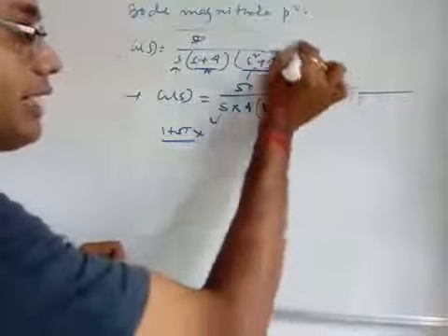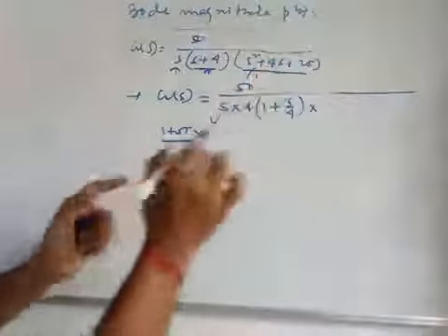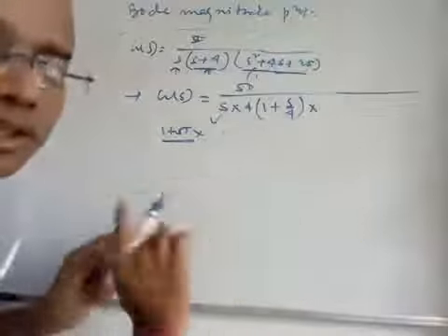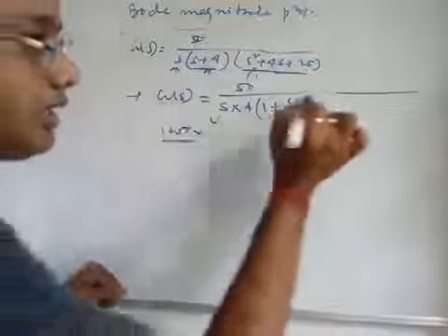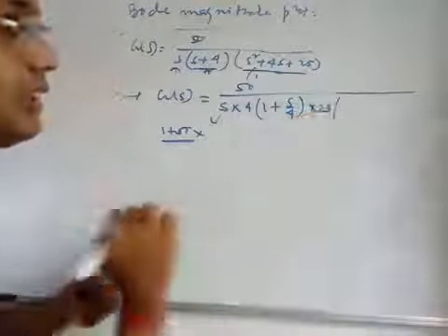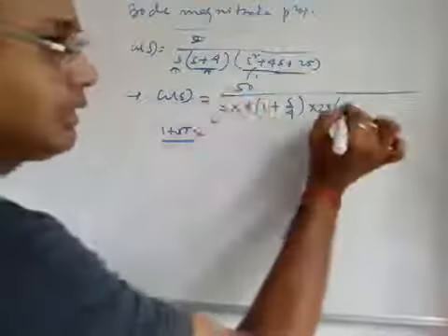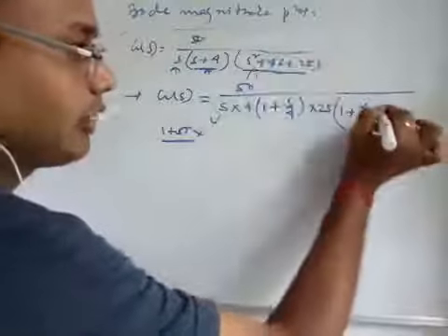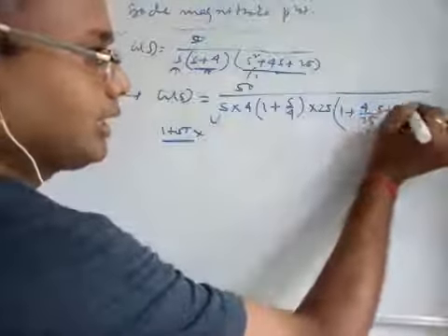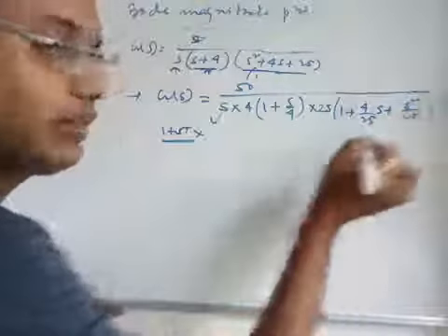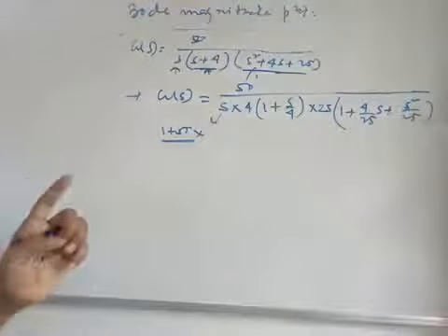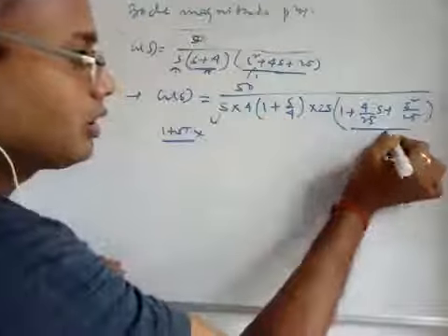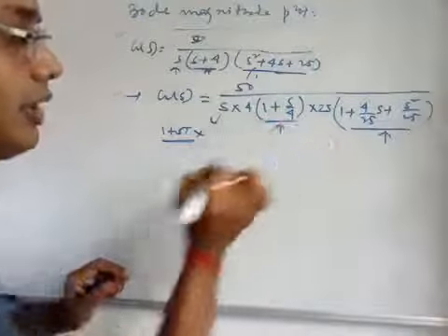And for the second order part, what is new here is that you have to take the form 1 plus s square like that. In order to get that, we take this 25 out, and here you see 1 plus, I will write it like 4 by 25 s plus s square by 25. So there is no problem in it. Now this is the time constant form for the second order factor, and this is the time constant form for the first order factor.